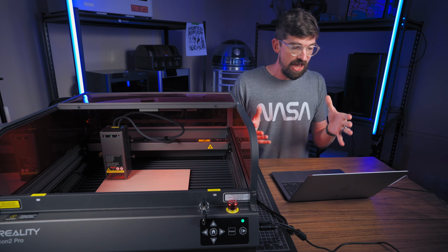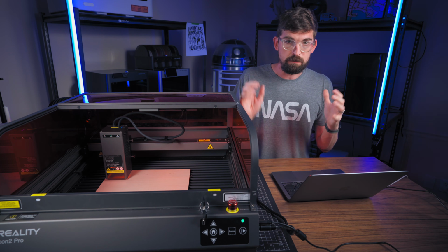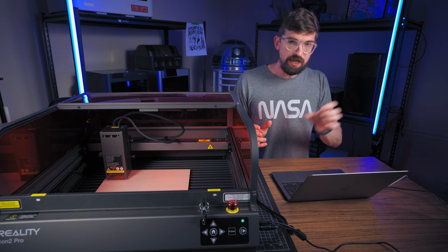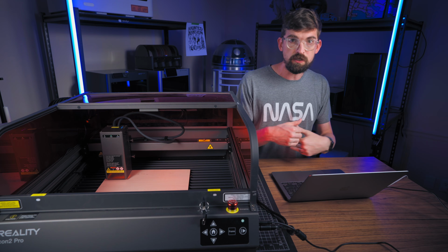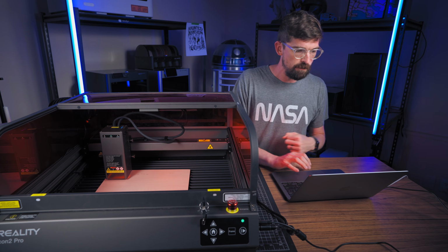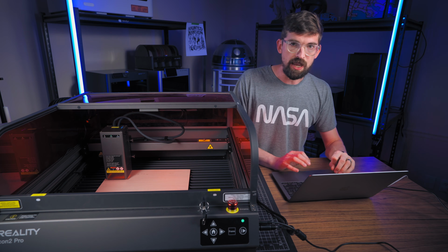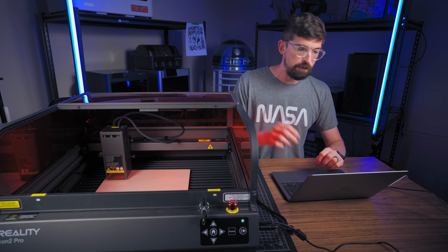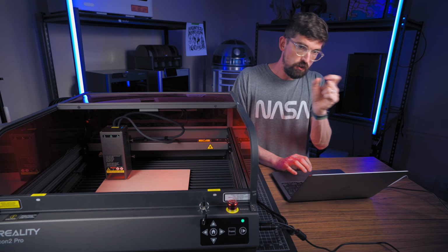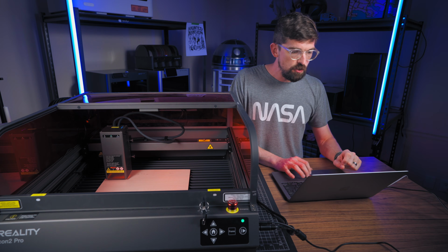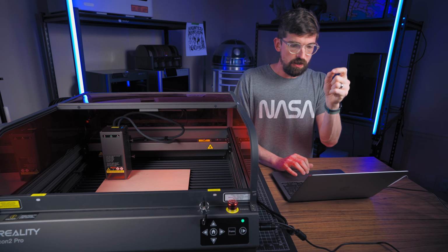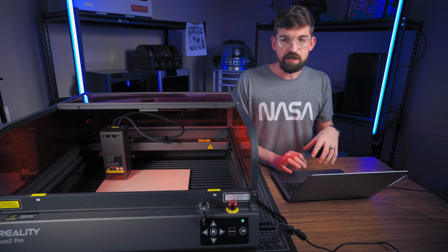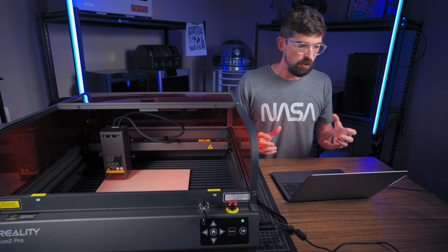I actually find if I have a vector as well as a bitmap to do that image, doing the vector is typically going to be better because a lot of times the way it does the math and the calculations can go faster. But you could actually do two different operations. So you could do the normal engrave, but then you could do a really light pass at the end that just does the outline, that I find gives you a really crisp edge to a lot of your graphics.